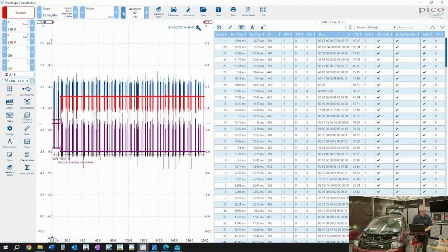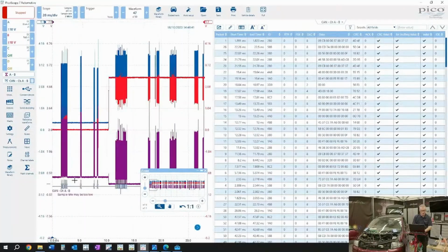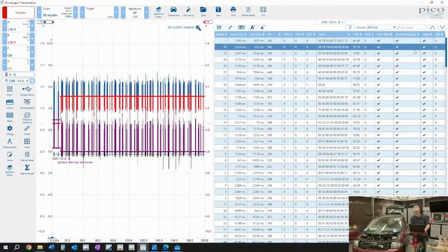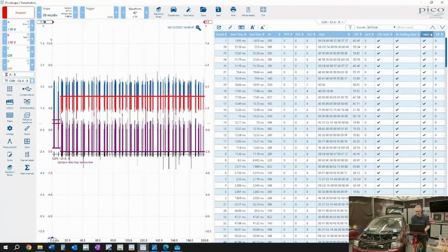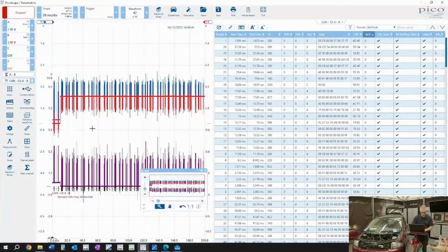There we have it. So you see here right at the beginning, let's zoom in. There was an event where the CAN packets were disrupted. So there's disruption there, which must, says he, have resulted in an error. So let's have a look. So by valid, okay, let's go for acknowledge. Surely not. Okay, well, let's have a look why that was the case, because we can actually see the packet. Let's just zoom in right at the beginning.